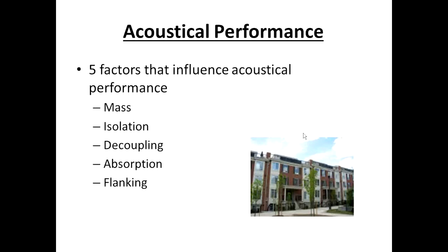Well, that phenomenon occurs in partitions, and that's what really hurts sound performance. So we need to decouple by design, decouple or cut the string, to make sure that those two masses, or what will eventually be layers of drywall, are isolated from each other and decoupled from each other.